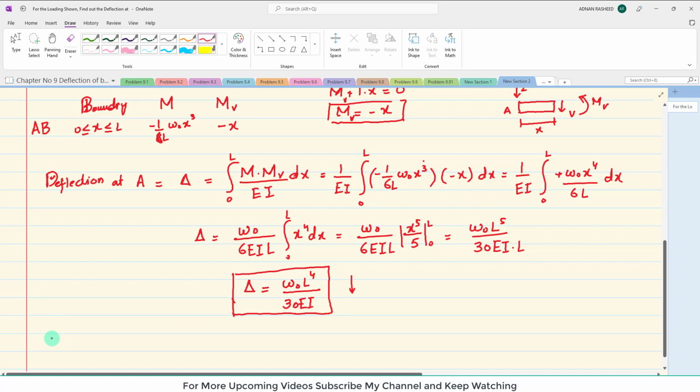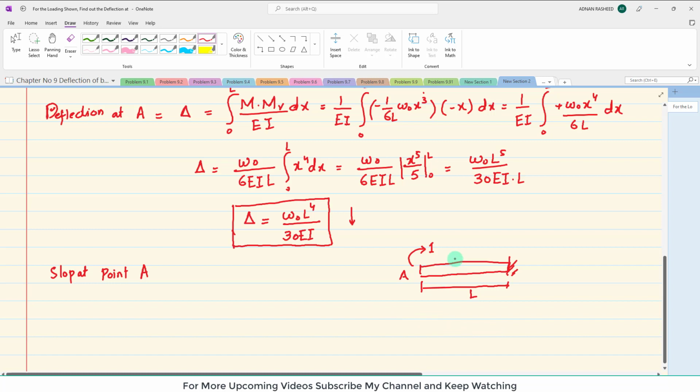Now we will move toward finding the slope at point A, or free end. For that you have to take the same cantilever beam. One end is fixed, total length is L. Now here at point A you have to give a unit moment, and again you will have to find MV.